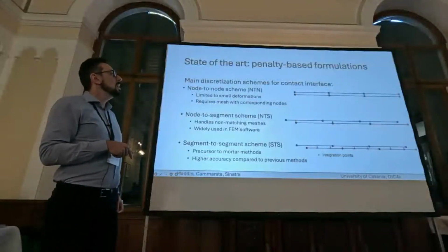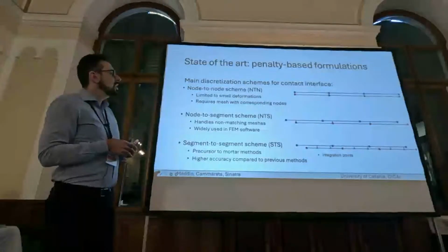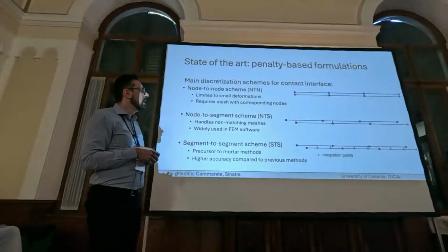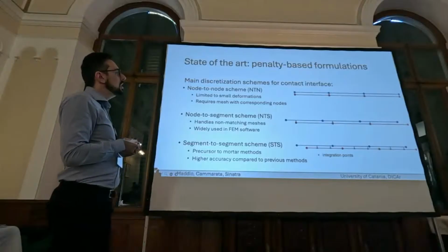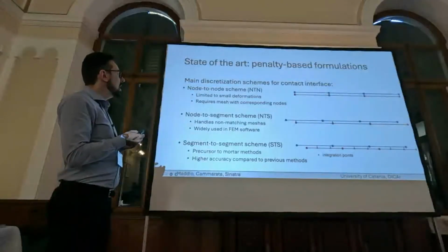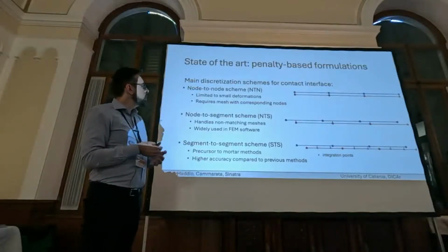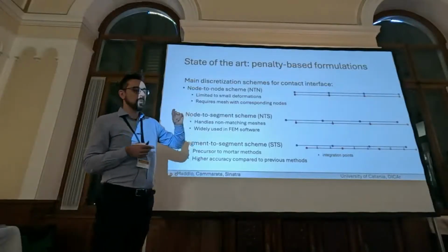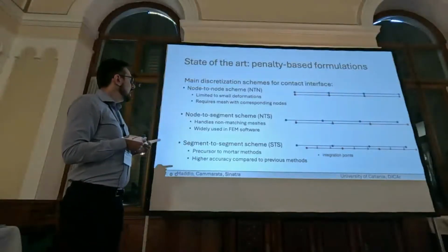Since we based ours on the penalty-based formulation, here are the three main schemes used for this contact formulation. The node-to-node scheme is limited to small deformation because we need to match the nodes of the two bodies.